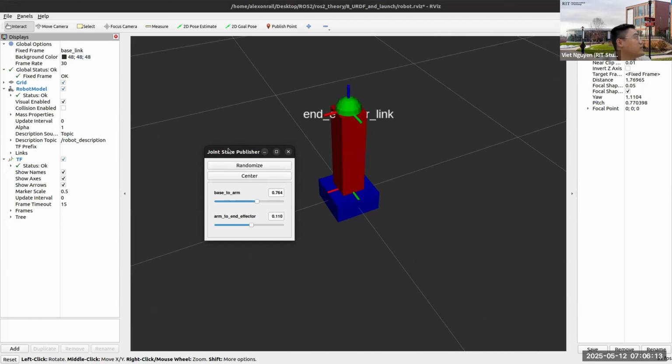So underneath this joint state publisher is also a node, right? As we have talked about, a publisher node, where it publishes to a topic. And then this RViz or launch will launch another node called subscriber. And then that subscriber will subscribe to that topic and listen to the joint state commands. And then that will control the URDF inside this. And then the RViz node will listen to everything, the robot's joint states, and then it displays onto this screen right here, visualization.